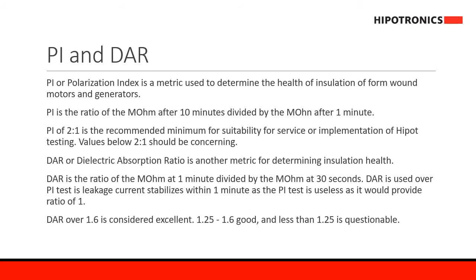On the other hand, for any PI value between 1 and 2, it's a questionable insulation condition. For 2 to 4 PI values, the insulation condition is good. Any PI value over 4, you have an excellent insulation condition.